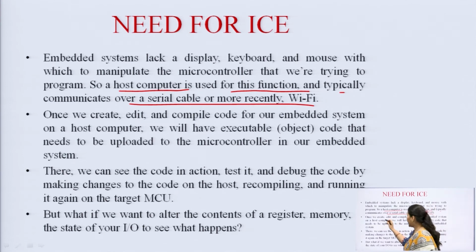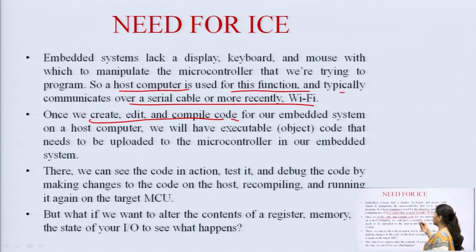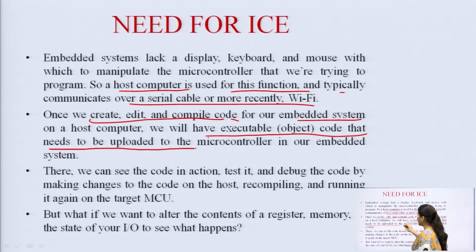Once we create, edit and compile the code, all these essential processes have been completed for our embedded system on the host computer. Then we will have executable object code that needs to be uploaded to the microcontroller in our embedded system.